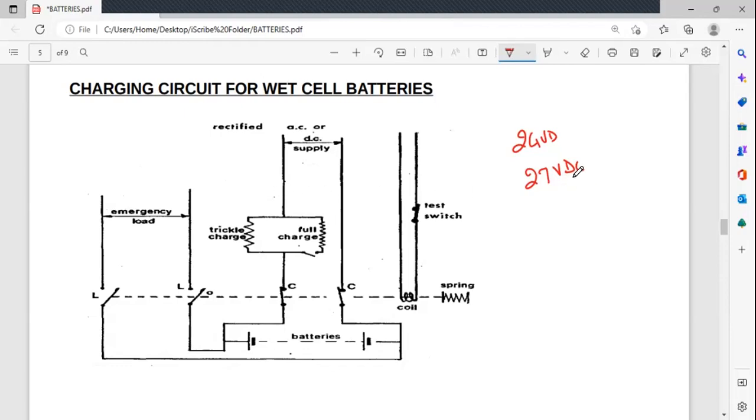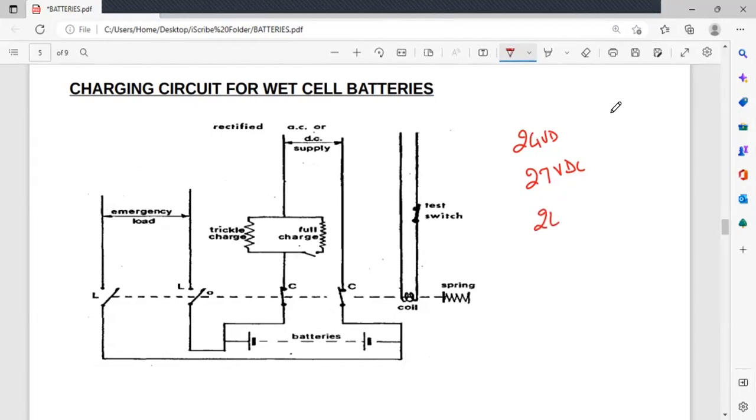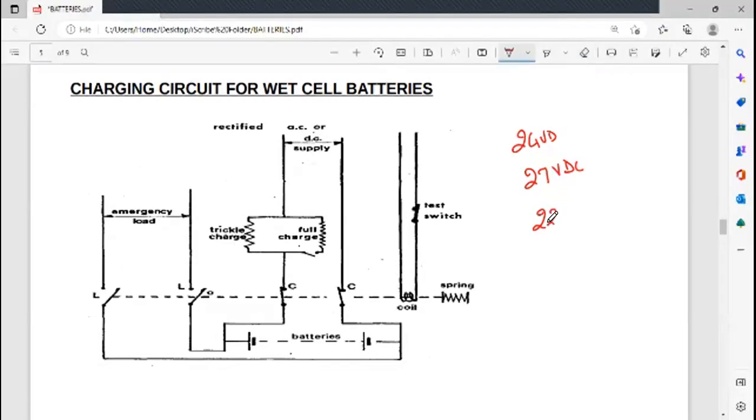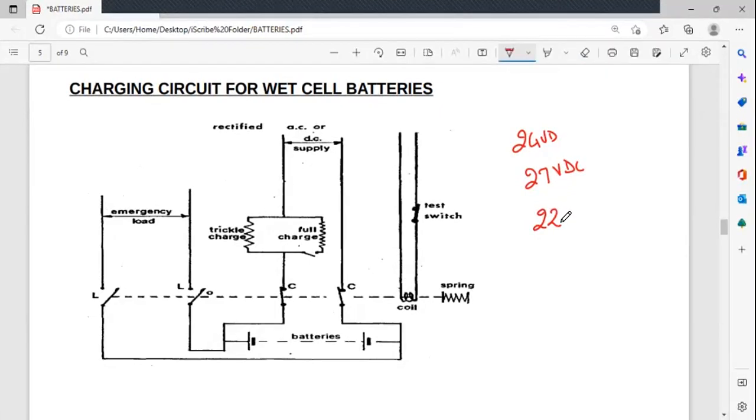But if your voltage has dropped to say 22 volts, the trickle charging circuit will sense it has dropped below this, so let me make more current flow through this and bring it back to at least 24 volts, if not higher. It should not cross this. So that circuit during your trickle charging time will give an extra current.